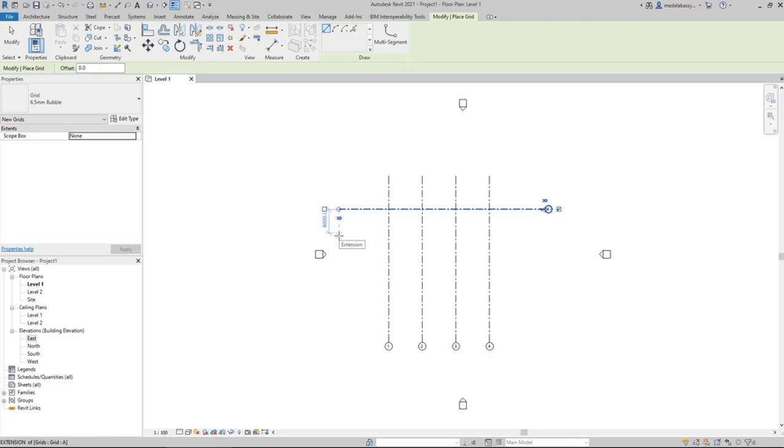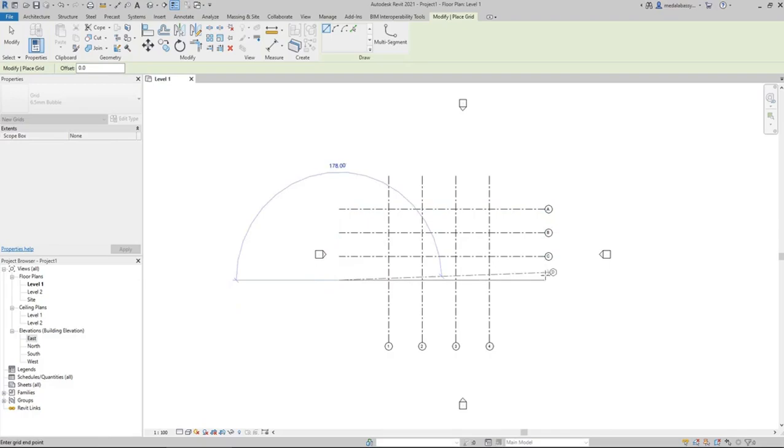Either you rely on the guiding spacing in blue when you move your mouse, or you can just do it the same way. I'll do it again. So now let's go with 7000 here. And then you get the spacing, and then you can turn it back to 4000, and it will tighten the spacing to 4000 instead of 7000. The last one would be here, and then that's it.